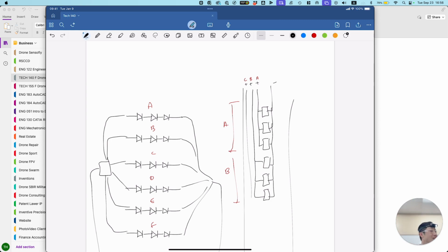I take that back because the first 2 is okay now. So you would just have to do, how many more segments do we have? We have 4 more segments plus a ground. Actually, the ground I've already connected because one of these is valid. So we just have to do 3 more. Not the worst thing in the world, but you're going to have to deal with the 26 gauge wire that we have here. I think we used 22 gauge wire here. So you're going to have to use that one. Give it a shot.